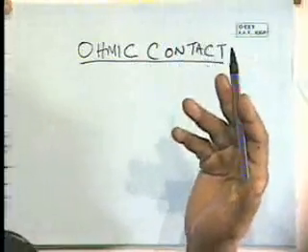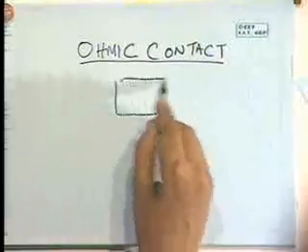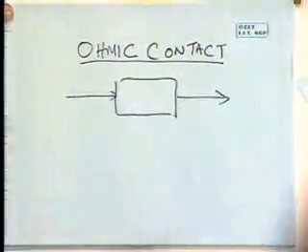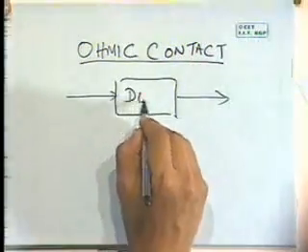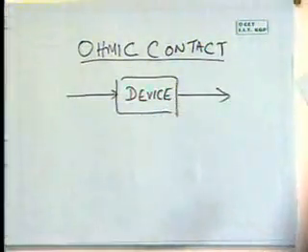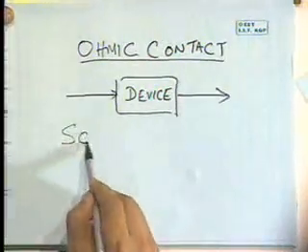be linear. Now, strictly speaking, in a real contact, that is not true, or may not be true, I should say. You may have some degree of nonlinearity, but the main point is that the contact resistance, that means the resistance that the contact offers to the passage of current through it, is insignificant. Because otherwise that will become the current limiting factor rather than the device performance itself. So those are what are called ohmic contacts, and I will come to that later simply to say it's a means of getting current in and out of the device without affecting the performance of the device. That's basically what an ohmic contact is.